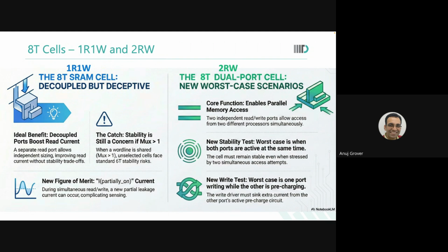So there is coupling that has come even before. See, the same thing I told you about precharge, the selective precharge. There's a coupling that has already come before your read operation started. You're starting from a lower BL than VDD because precharge was off and there is coupling coming. Can you control what was written on the other side? No. That is random data. So it can come in whichever way.